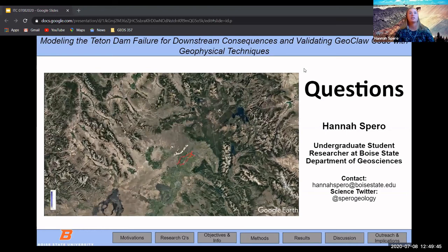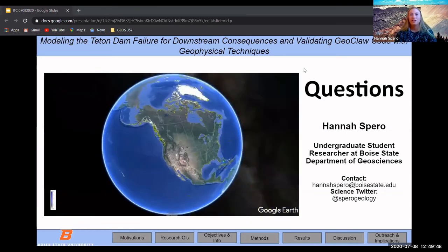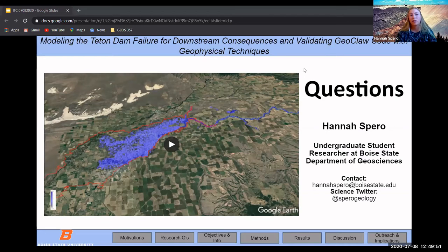That's a really good question. So I'll answer it in 2 different parts. For my expectations of the runtime, I would expect it to potentially add between 15 to 30 minutes of extra computation time. And answering the second part as well, the adaptive mesh refinement focuses on only computing the gridding within the area that you're interested in. So although we might have high resolution topography for a large area around the dam failure with the drone photogrammetry campaign, we will be able to focus our sites specifically just on the reservoir in question and on the dam failure phase.